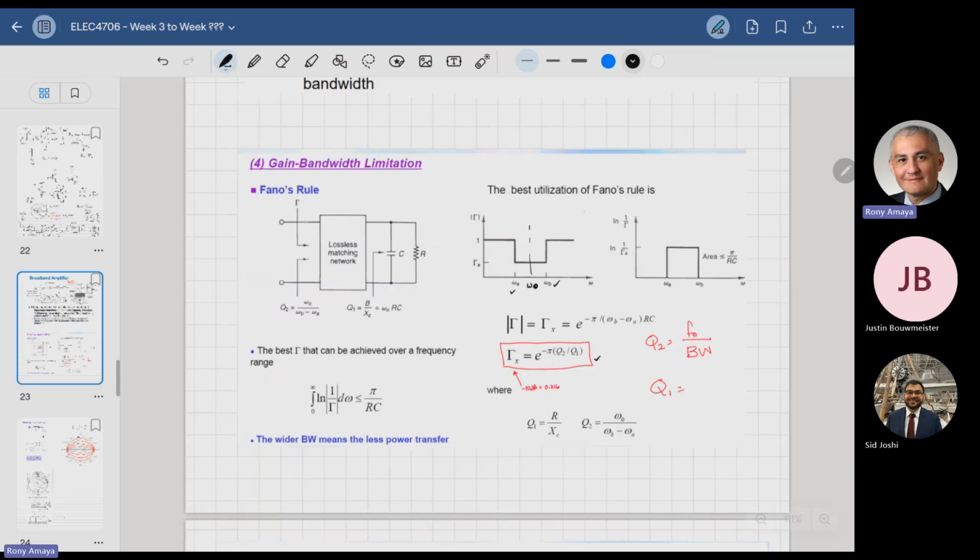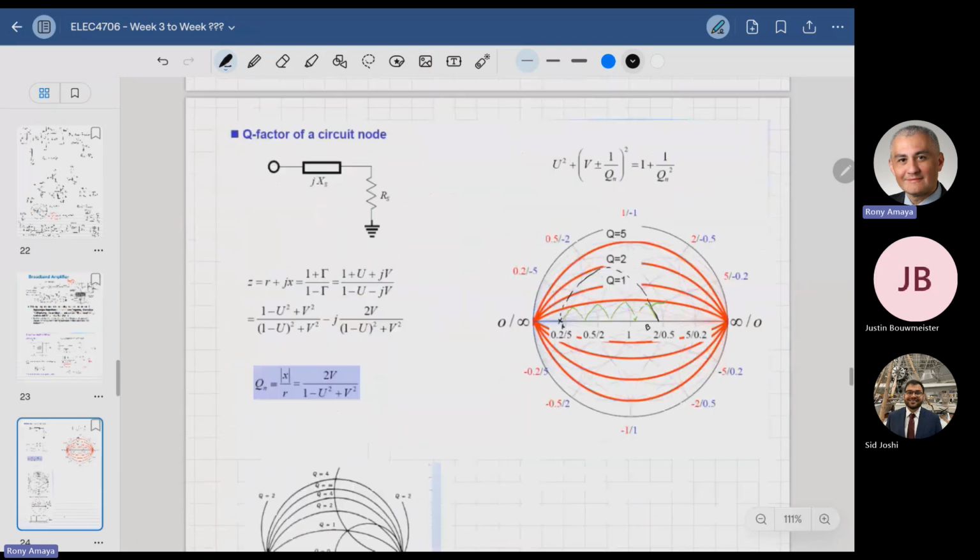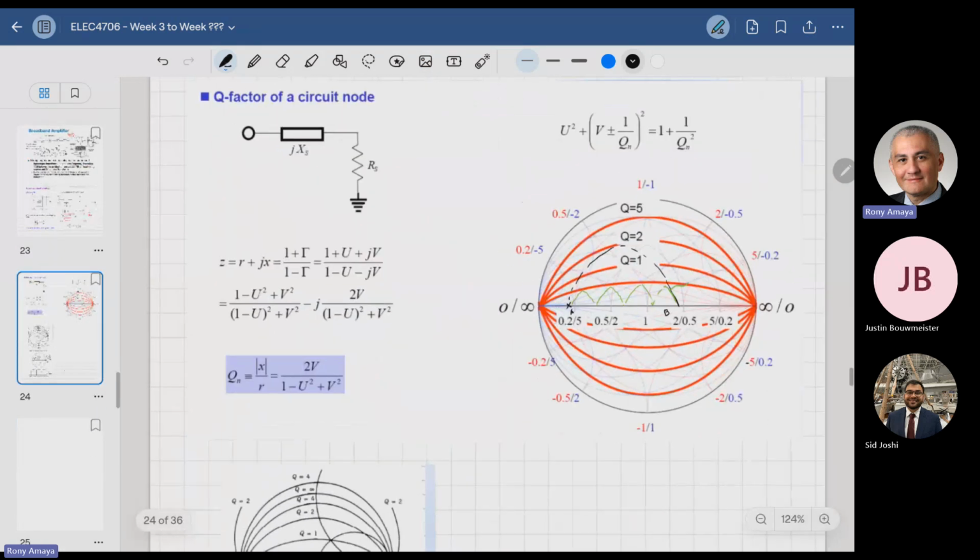So effectively, what we have to do here is either reduce the reactance or deal with the actual requirements that we have for bandwidth, right? It's a very powerful thing, and you often see it and just bypass it without really understanding the principles. We're not really going to get into this as much, but looking again at a visualization tool like a Smith chart, it also tells me that I can not only plot impedance levels, but I can also plot Q circles.